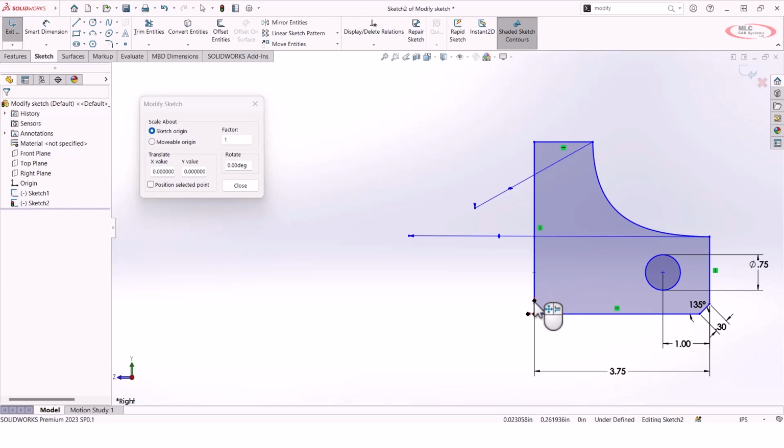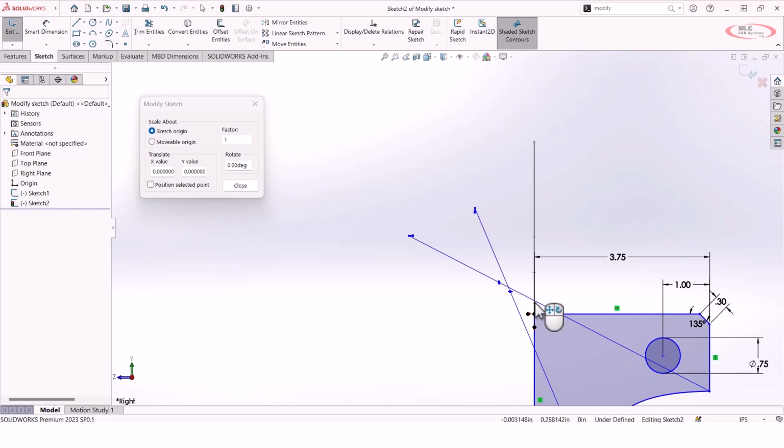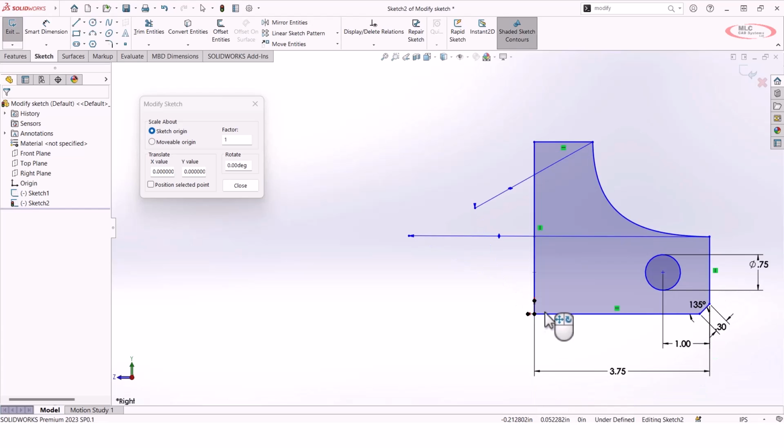Likewise, if I go up to the top point in that little XY coordinate system and I right-click on the point at the top, it will mirror it across the other way. So it's a really neat tool that allows you guys to manipulate sketches in their entirety. I use this a lot whenever I copy a sketch to a new sketch plane.